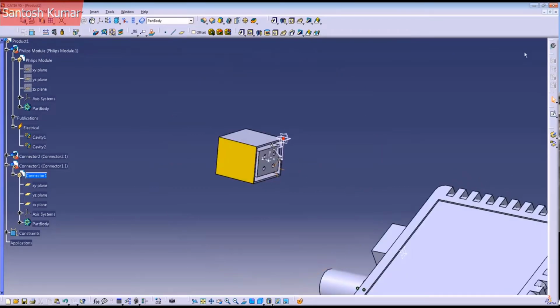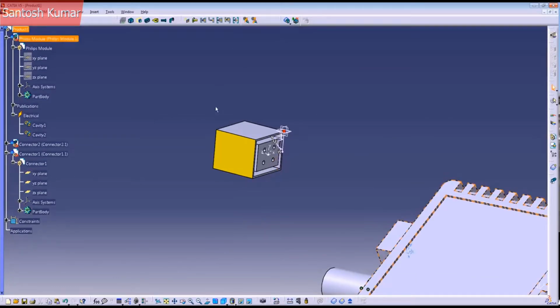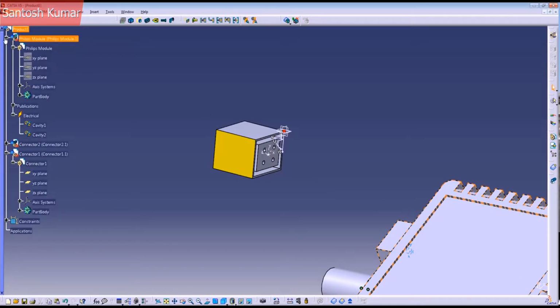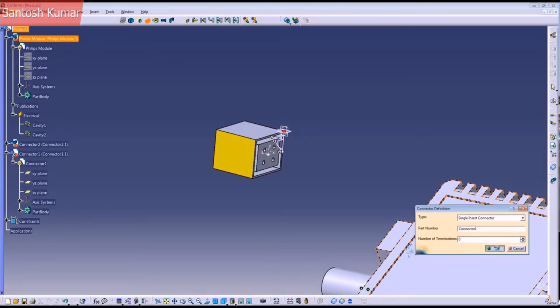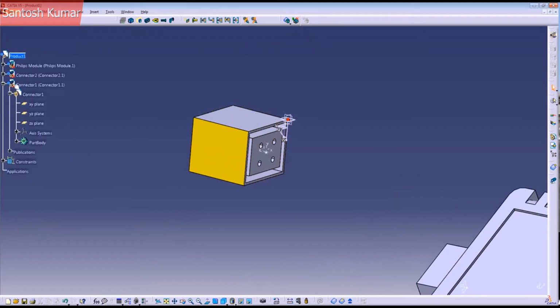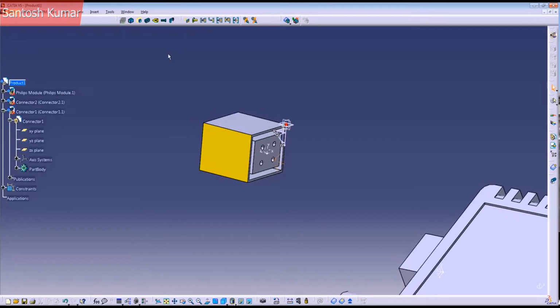And now, okay, let's go back. Double click the top of the product to go back to the electrical workbench. Now let's define this one as a connector. Select the connector, okay. One thing to make sure: if the icon changes, it means you did it right. And now let's go to select, and define cavity connection point.